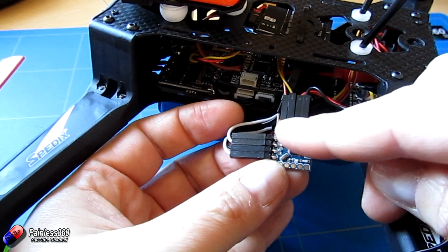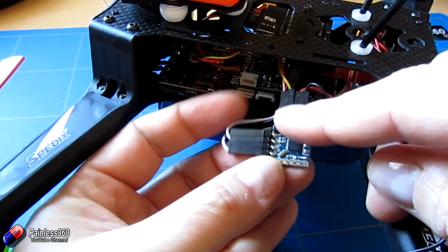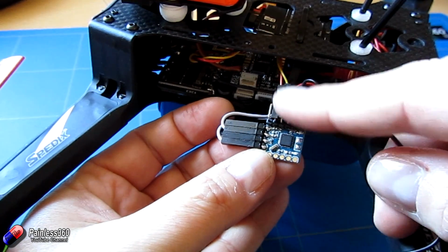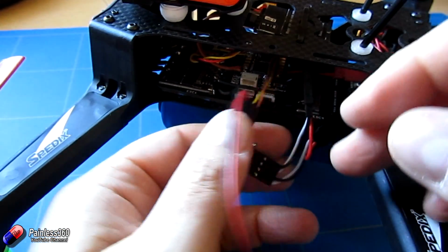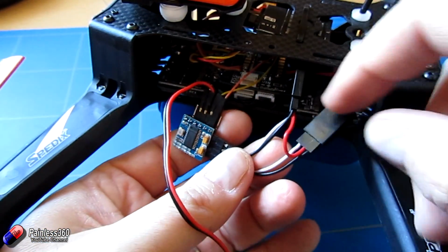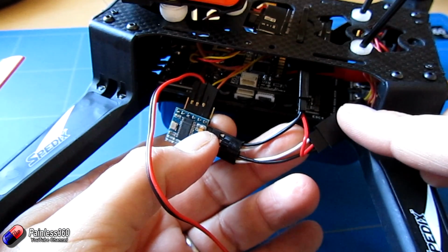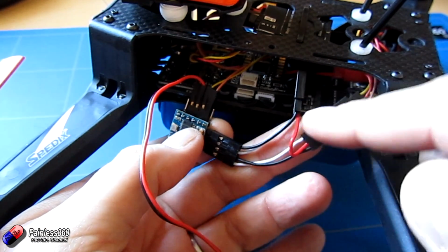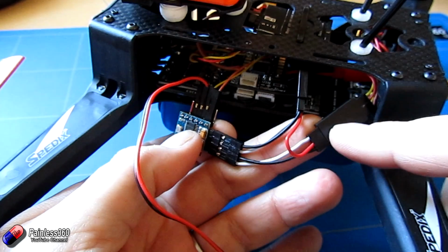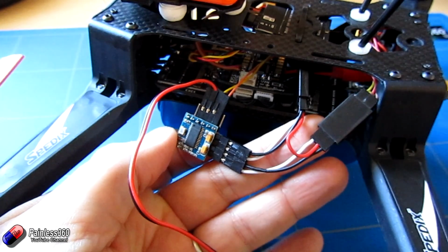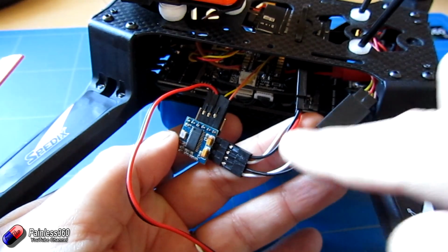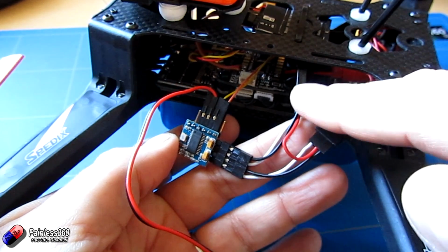Then we have the receive and transmit wires from the KISS flight controller coming in here at the top. That's bringing in the data. And then the last bits here, of course, are these cables that are connected into my FPV transmitter at the back and my camera, and there's that little red wire connecting the two together. So that's how it's all wired up. Relatively straightforward. And if you make these little adapters, it means I can just unhook it.